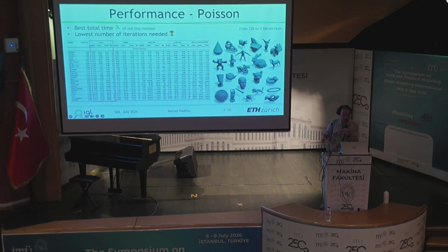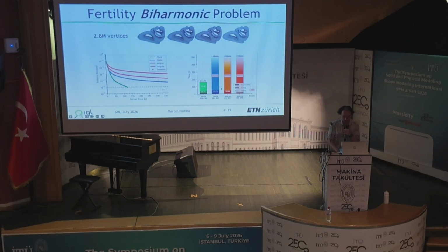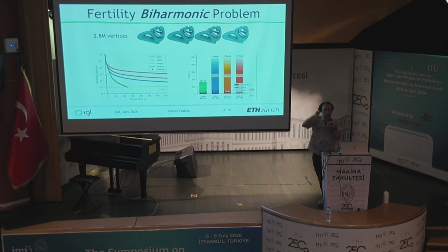Yeah. We have tested this on plenty of meshes for performance. And generally, after 100,000, 200,000 vertices, our method starts to win, not just in build time, but in total time. So this is important because a lot of multigrid methods are designed to solve faster, but the build time is sort of considered to be separate because they think of, oh, I want to run a thermal simulation, so I only need to build once and then I solve all the time. What I'm presenting here is something where the build time together with the solver time is actually very good.